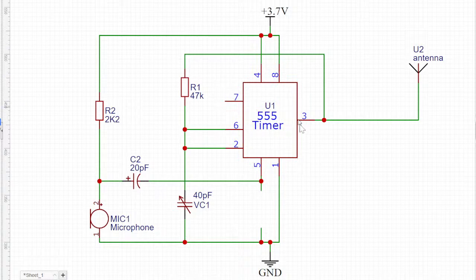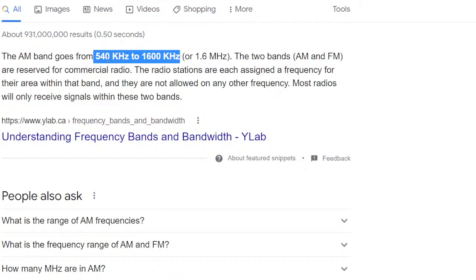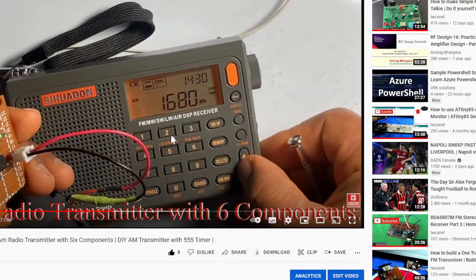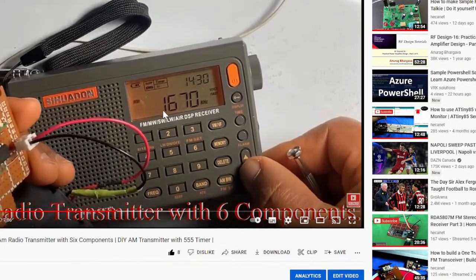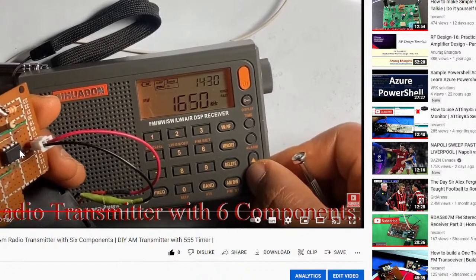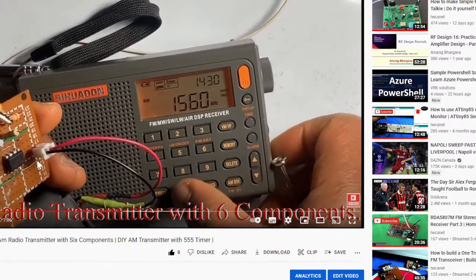555 timer that you got. Some of them can get up to 3 megahertz, the newer ones. Some of them can get to 2 megahertz, others can get to 1 megahertz. The good thing is the radio we're building here, the transmitter we're building, is for an AM radio frequency band, which is just between 540 kilohertz and 1600 kilohertz, or 1.6 megahertz. And you saw in our transmitter, the transmitter was actually transmitting to within 1700 kilohertz. So the 555 timer we're using is the one that can reach about 2 megahertz.